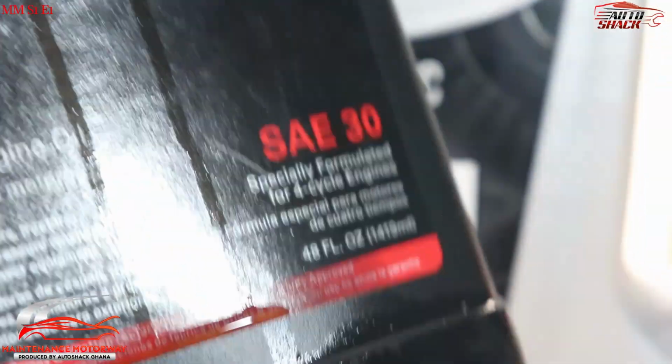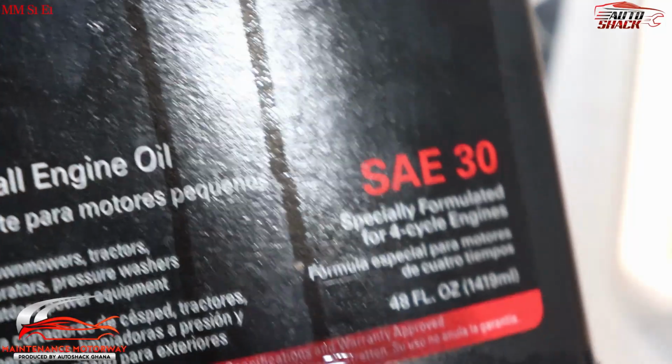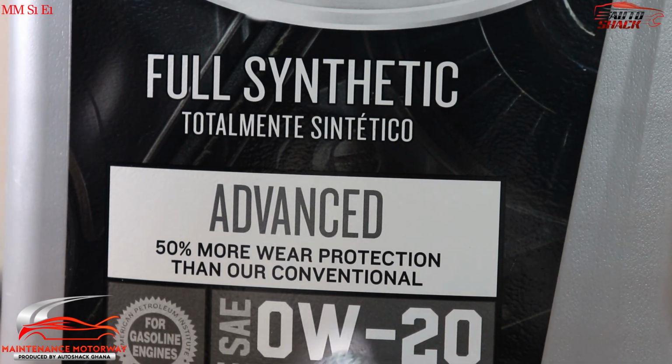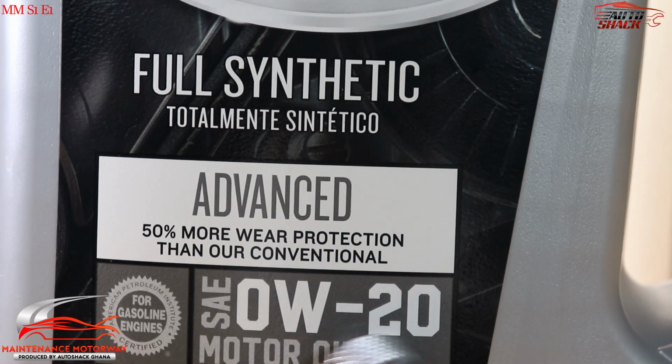Now, if you look quickly at this oil I have here, this is oil for my riding lawnmower, and you can see that it's just SAE 30, so it's just one viscosity. That tells you that this oil is thicker than what this one will ever be. So depending on the kind of engine that you're running, you choose your viscosities. That's why vehicle manufacturers are very particular about the viscosity they choose for their engine, because they know exactly how they made the engine and what kind of oil will work for it.